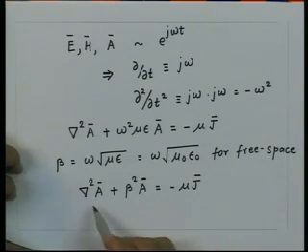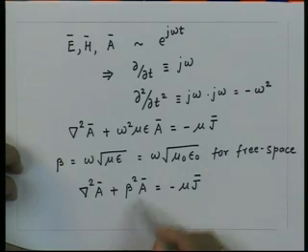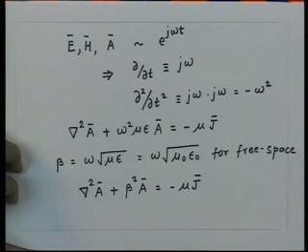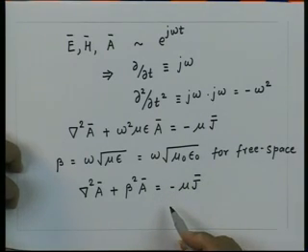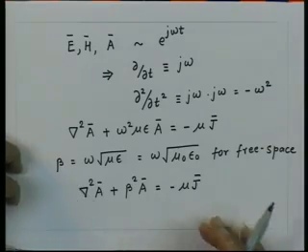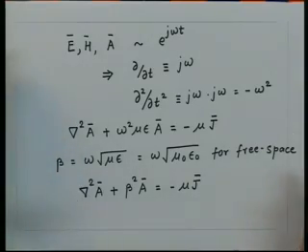So, first what we do is we just convert this equation by replacing this quantity A by a scalar quantity and the right hand side by a delta function in space, and whatever solution we get to that system, we say that is the spatial impulse response of this system. And once we know the impulse response, then we can always find the response for any arbitrary source, and that will be minus mu into j.